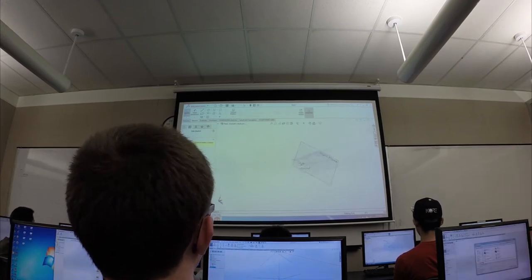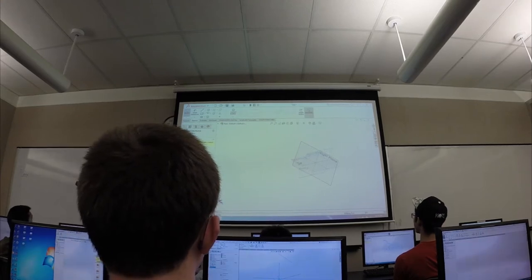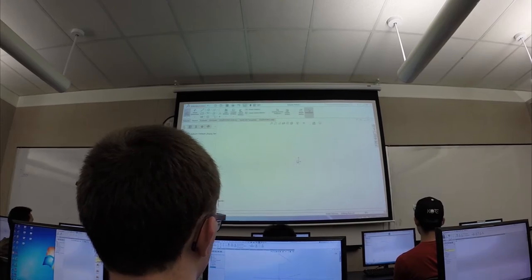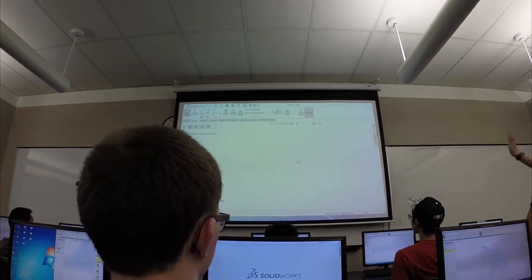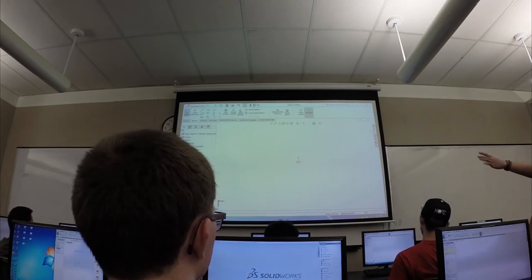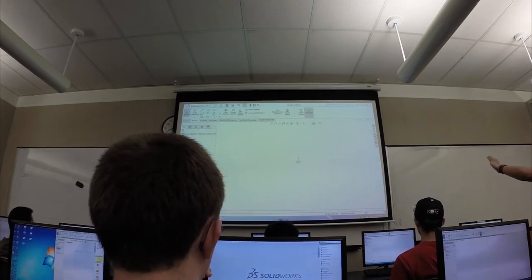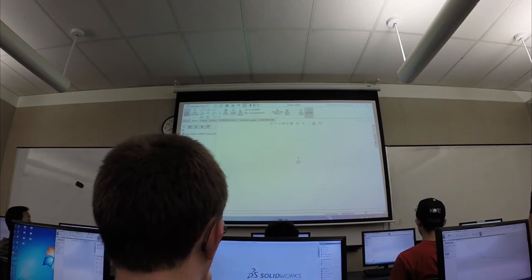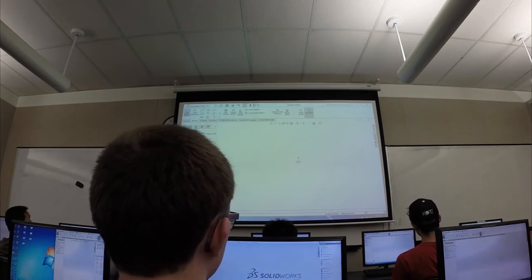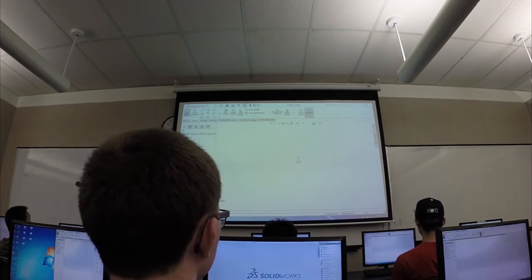So you'll know the top plane is selected when there's an orange outline around it. So click on that. As soon as you click on it, the view becomes orthogonal to that plane, so kind of perpendicular, right? So you're seeing top down to the plane. It makes it easy to design, and you know your dimensionings will be absolute and not at some skewed angle.